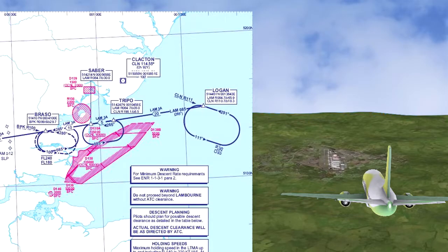Most aircraft are able to navigate along designated flight paths all the way to their destinations more than adequately. However, at major air traffic hubs, such as the confluences of airways or the arrival and departure catchment areas of major airports, radar controllers will directly control aircraft position and track. This is called radar vectoring.